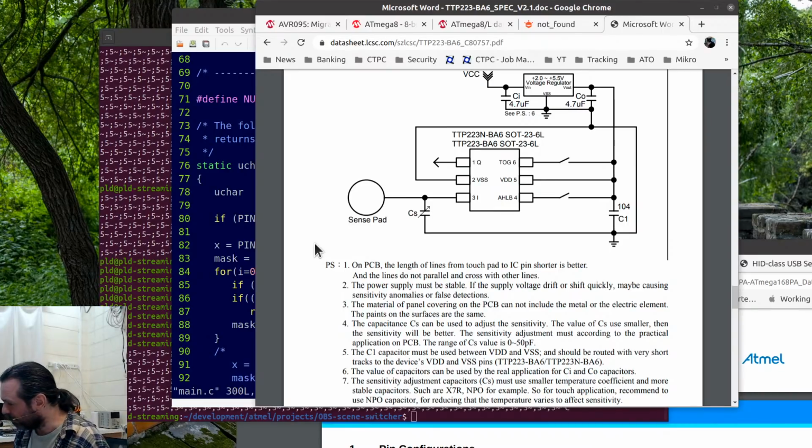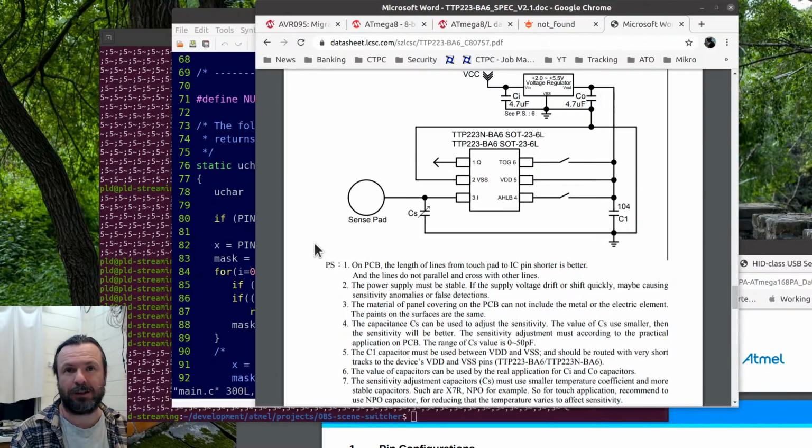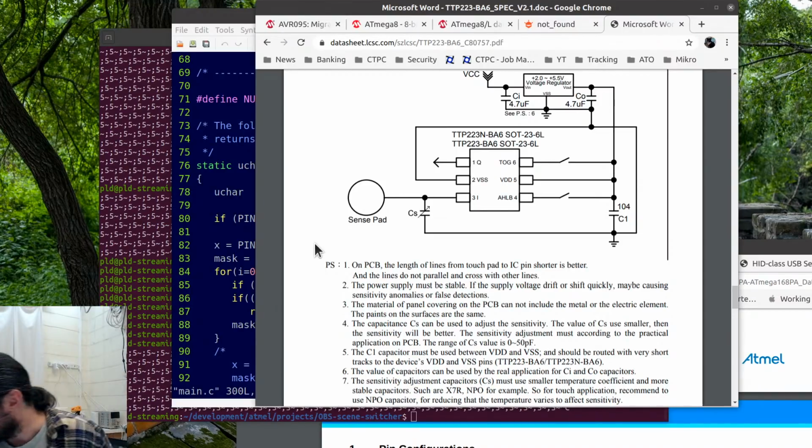I'd say we put a 50 picofarad on there. With it floating like that, it's going to be picking up, particularly around here. There's a lot of EMF, with things like the hot air station and everything like that. So definitely, I'd say 50 picofarad would be a good start. It looks like it's a 603 size or 402. I don't care.